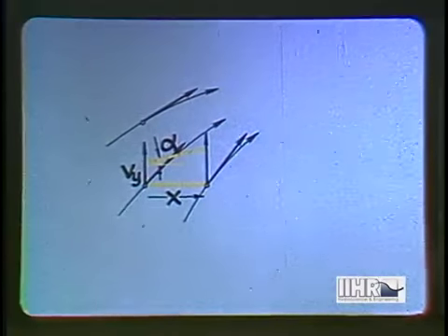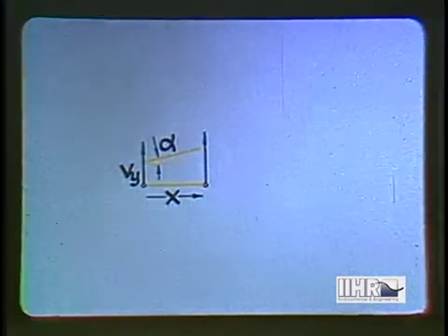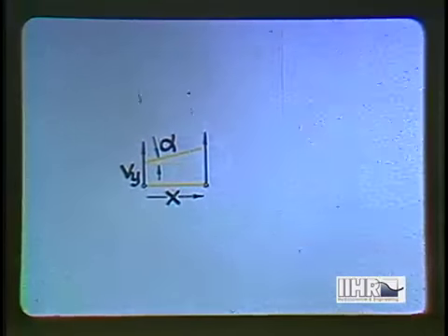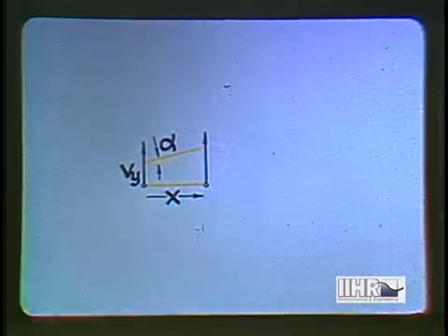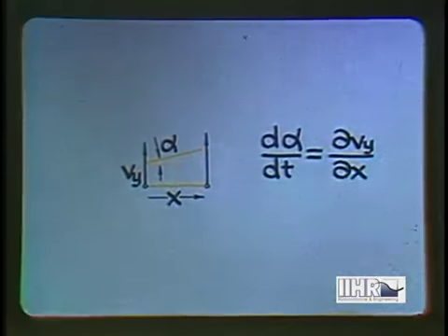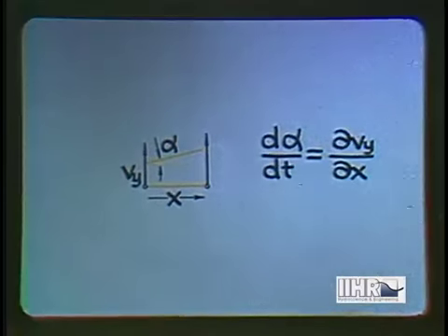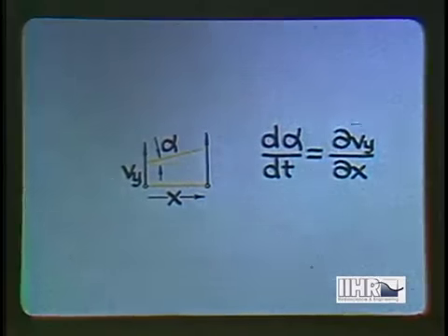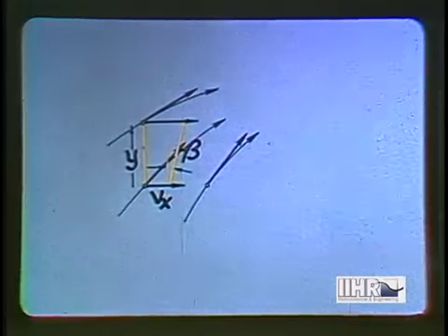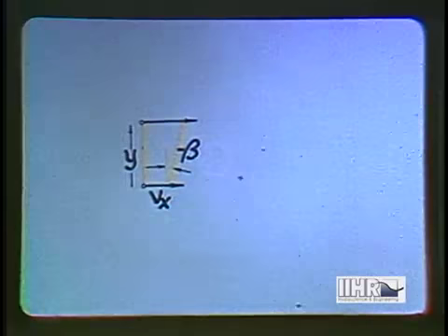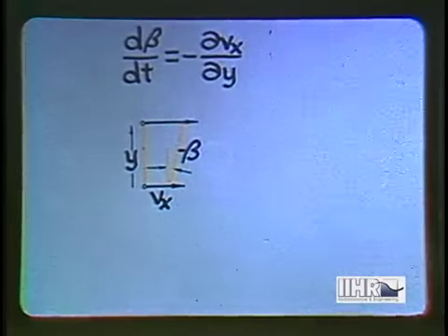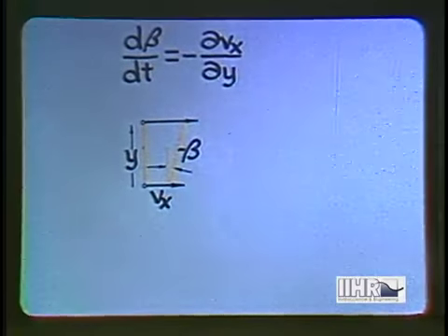It is then necessary to define it mathematically in terms of the velocity gradient. If the component of the velocity vector in one direction varies with distance in a normal direction, then the two ends of a line or a floating matchstick, normal to the velocity components, will move at different linear speeds, and the line or stick will tend to rotate with an angular speed equal to the velocity gradient. The same is true of a line or stick in a direction that is perpendicular to the first, a negative velocity gradient now indicating rotation in the same positive sense.